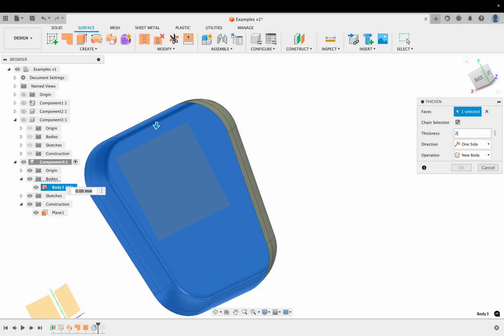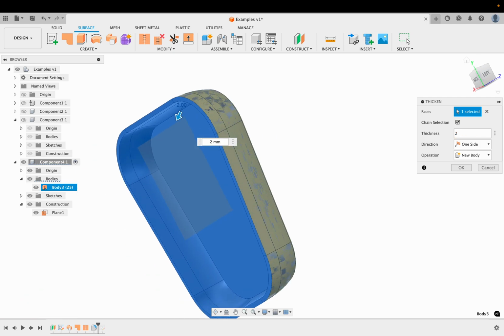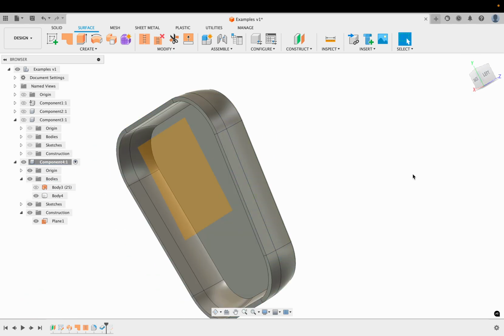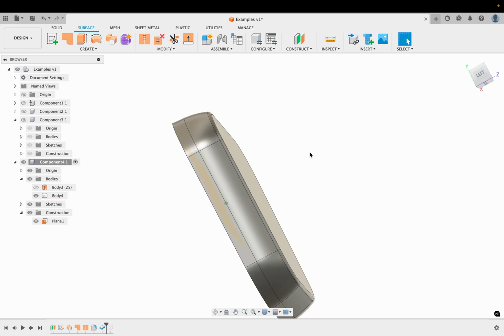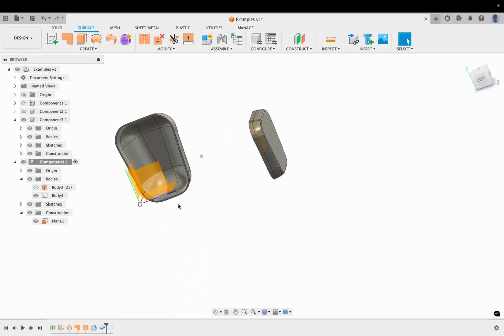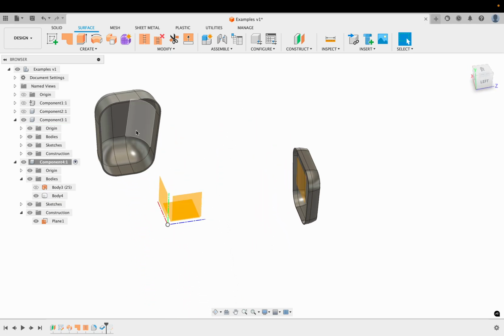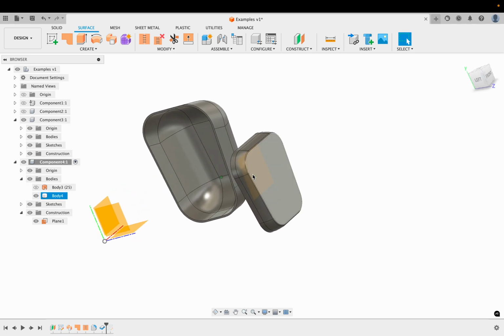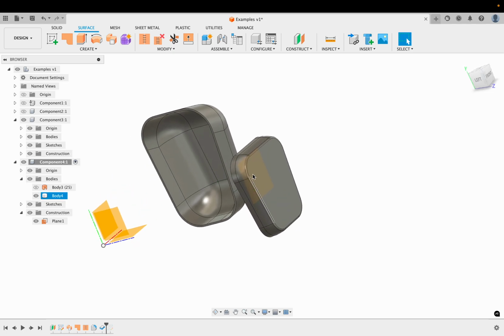Sometimes you will run into problems here as well. If the thing sort of self-intersects, you will have problems too. But now I also have a shell, right? Which is made in a very different manner than the previous shell, which was the massive shelled out. This is the refined surface modeling and thicken, right?